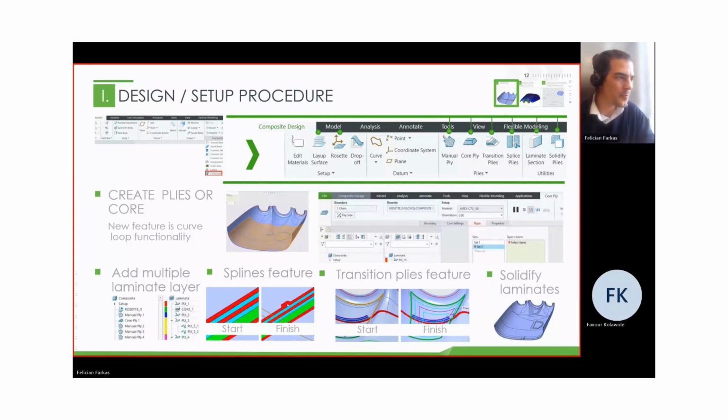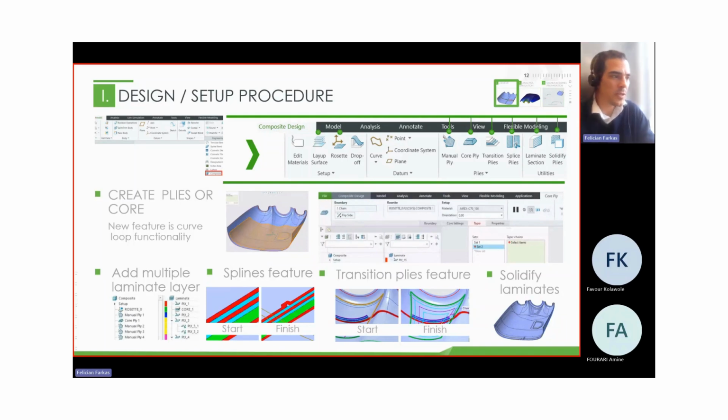And at the end, when the composite design is ready to solidify, we use an EML quilt, which includes all the layers, and we can use them as a solid model to do a two-part mold for the vacuuming process, or make some mass property calculations.